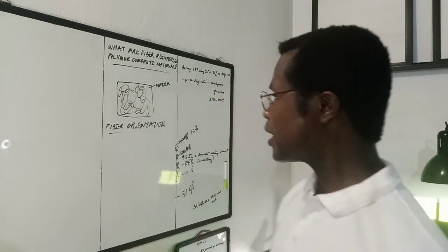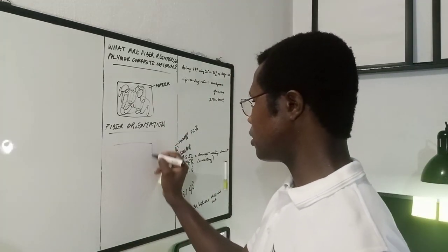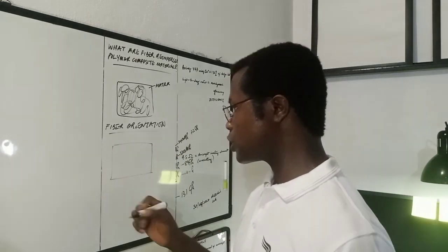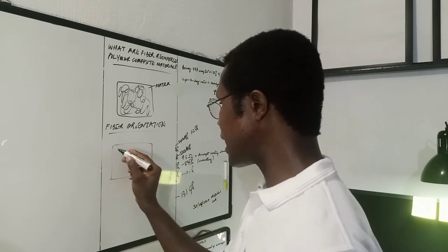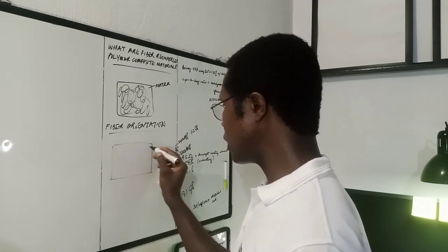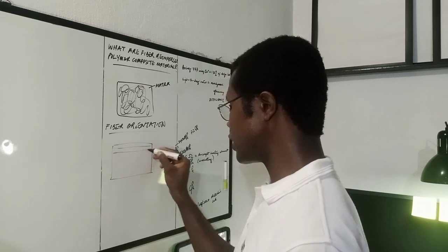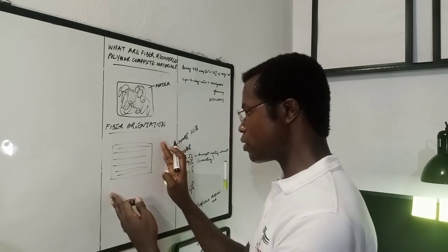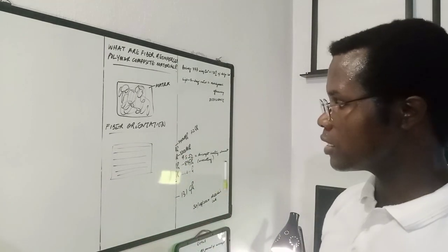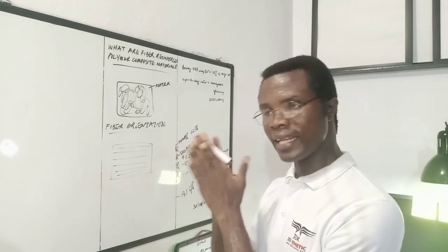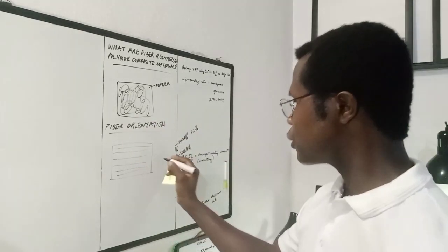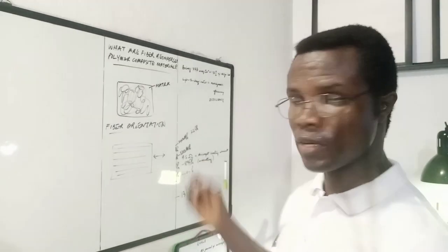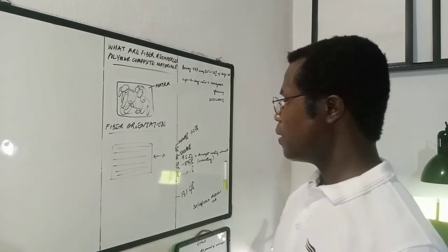Now, the way that a fiber is oriented inside a composite material matters, and it affects the mechanical properties. In the simplest situation possible, we can have a composite material with unidirectional fibers lined up in one direction. That's why it's called unidirectional. Let's assume a polymer composite is made with fibers very neatly aligned in one direction. You're going to have maximum tensile strength in this direction.